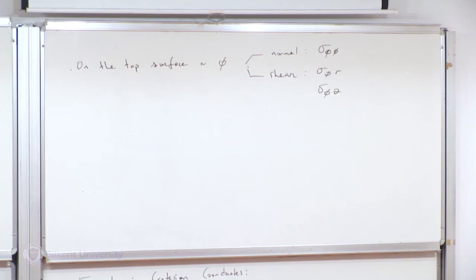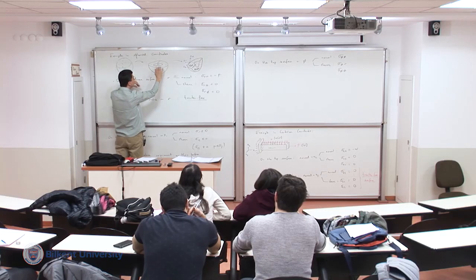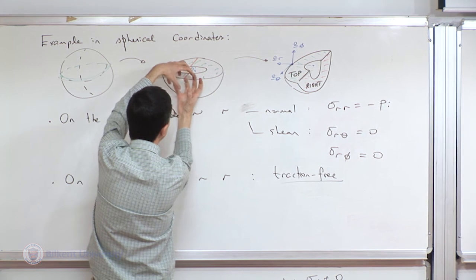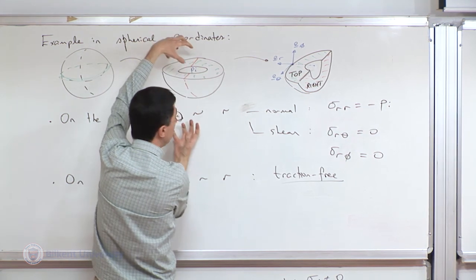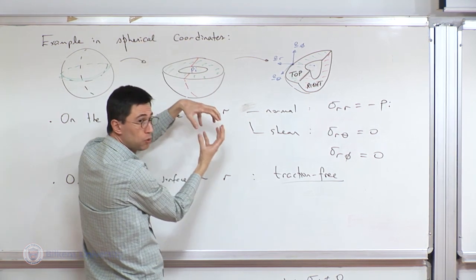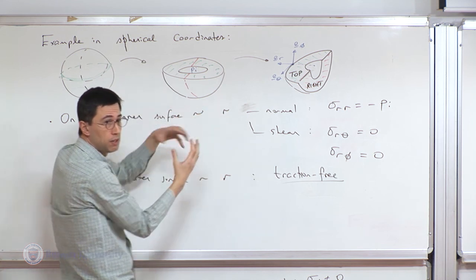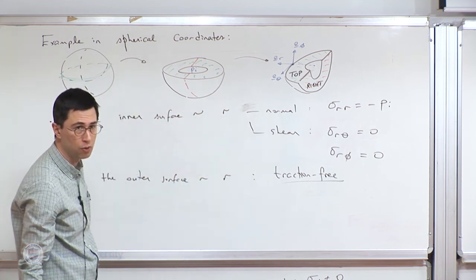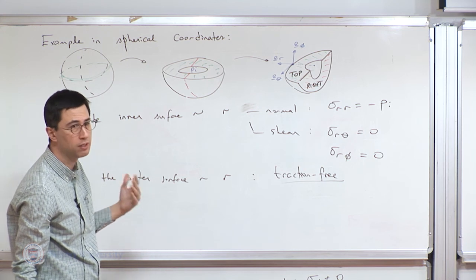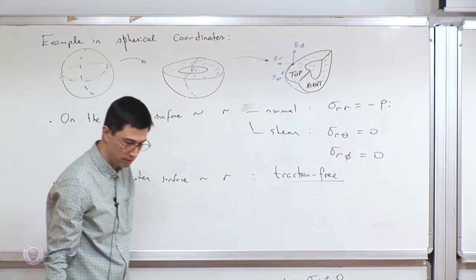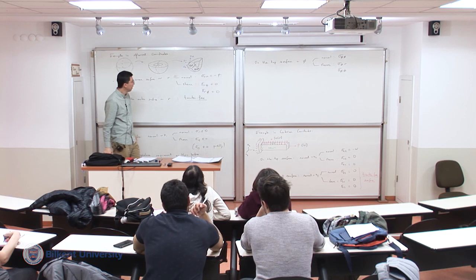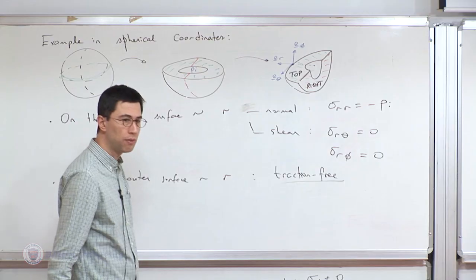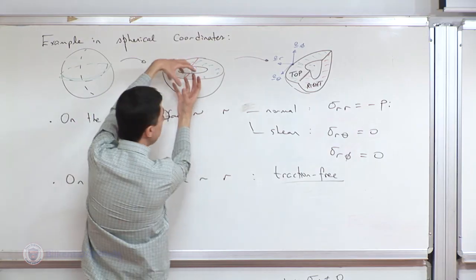So remember what the pressure is trying to do. Since we're talking about the top surface, you can look at this picture. The pressure is trying to split this thing apart, and what needs to hold it together are the stresses that form on that surface. So for sure something is non-zero, but is anything zero? As a comparison, I only have internal pressure.